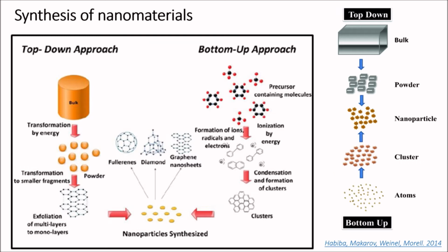In all the bottom-up techniques, the starting material is either the gaseous state or liquid state of matter. Various physical vapor deposition techniques like evaporation, sputtering, laser ablation, and chemical vapor deposition techniques like CVD, MOCVD, PECVD, etc. are the examples of the bottom-up approach.